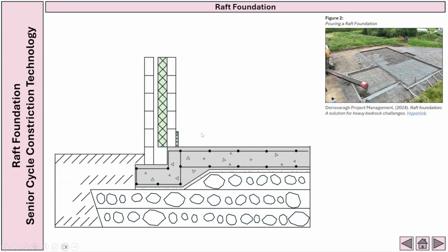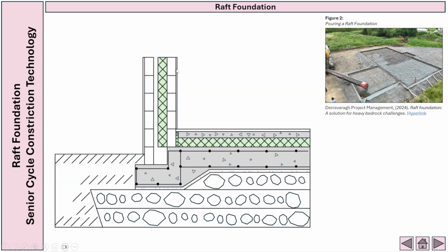Next, we're going to head on to the inside of the dwelling, and we're going to put in our 30mm of insulation, followed by our 100mm of insulation just here. And then on top of that, we're going to put in our 65 concrete screed. On top of our concrete screed and our 30mm of insulation is going to be our 25 flooring. Once the flooring is done, we're going to put in our 12 render on the internal wall and our 18 render on the external wall.